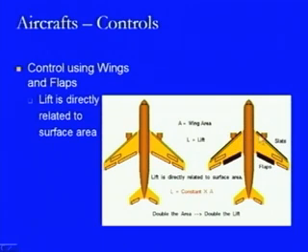So, this is known as slats and this is known as flaps, and this is wider and this is a little less wide. So, using the surface area being provided by these flaps, by tilting these flaps in the upward or in the downward direction, we try to increase the area at the time of taking off when it is required, whereas we try to reduce the area at the time when we are just landing an aircraft. So, that is one aspect which is related to the wings, as well as to the flaps and the slats being provided on the wings.